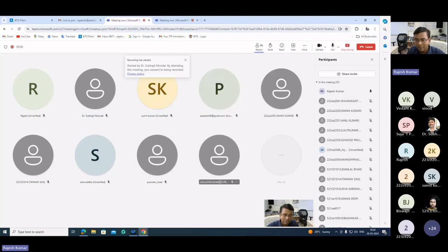While designing, you have to take care of stability. Okay, loss of stability. Then how to take care of that? First you have to estimate the loads. What type of load is coming on that structure? Whether that load is compressive or not. Bending is there, compressive load is there, dynamic load is there, static load is there. You have to estimate the types of load.